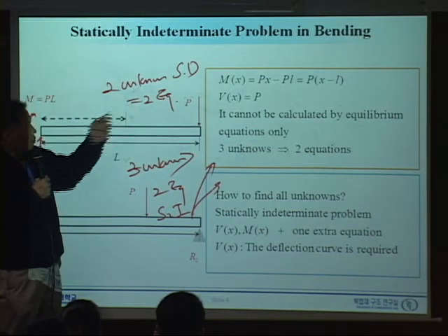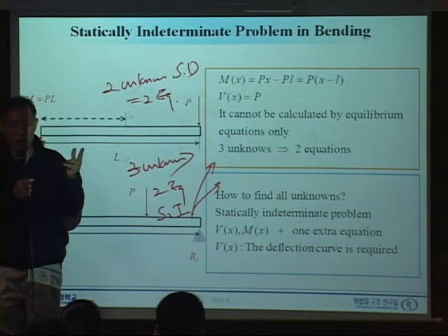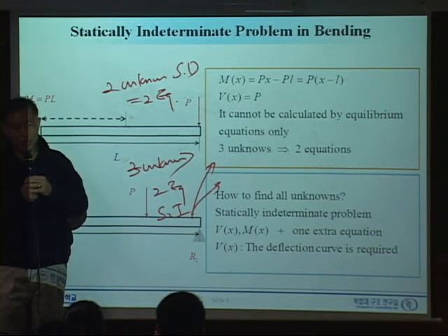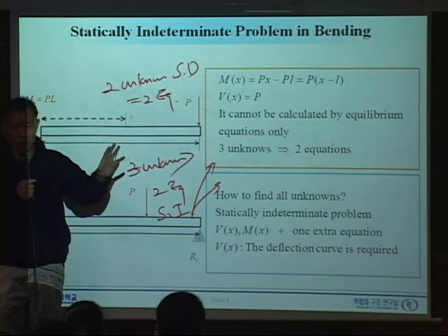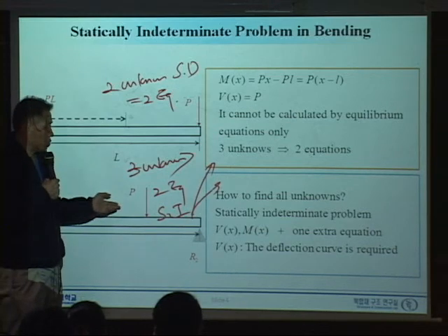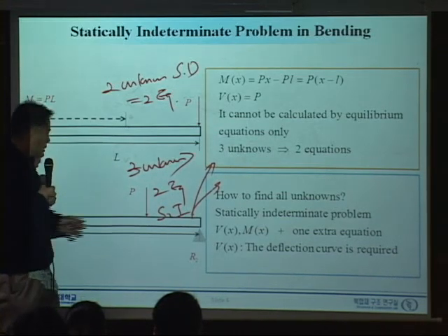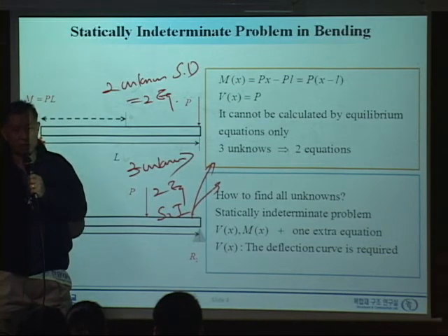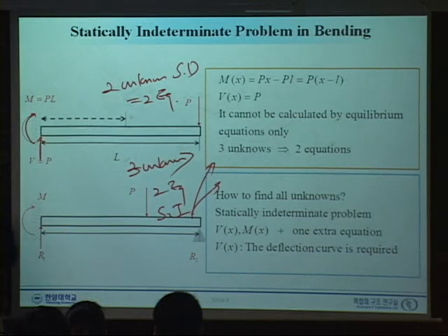Here we consider only the equilibrium equations, and we couldn't solve for the reaction forces, but in a statically indeterminate problem, in addition to the equilibrium equations, we will use deflection, and then we are able to calculate all the reactions, which are more in number than the equilibrium equations.